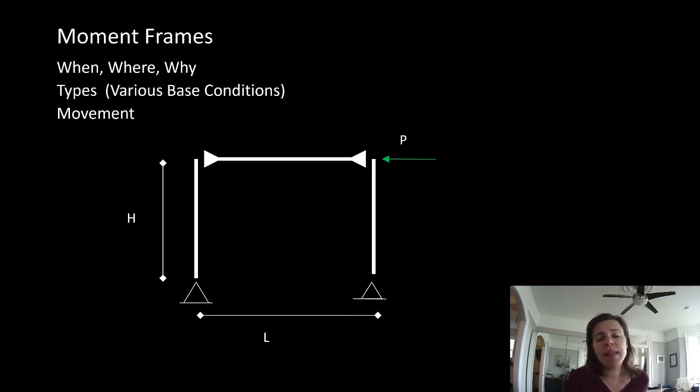So here's the interesting thing about moments, or loads in general. The stiffer the element, the more load it will attract. So if you have a system where all the elements are the same stiffness, it'll evenly distribute the load. And that is why, in that example we did, when I said that it would share the load out equally between these base reactions, it's true as long as these columns stay the same. We're going to see in a bit what happens when that isn't true.